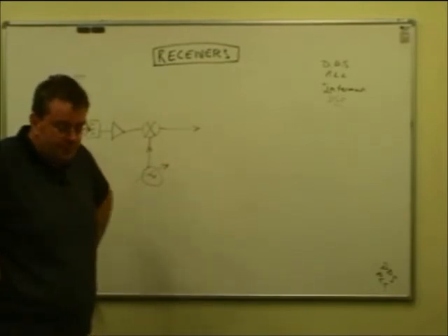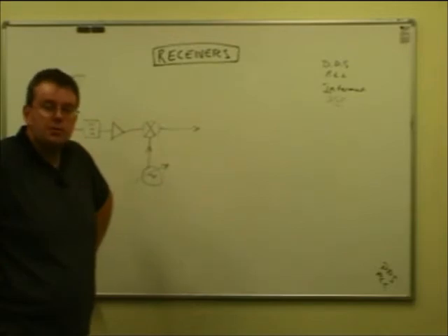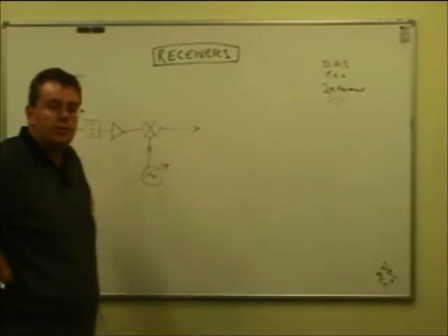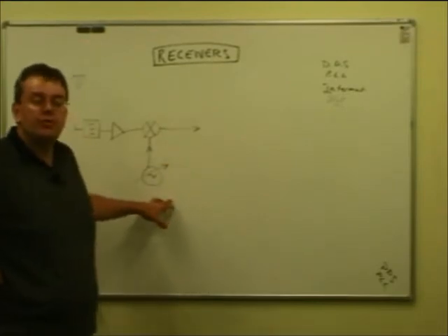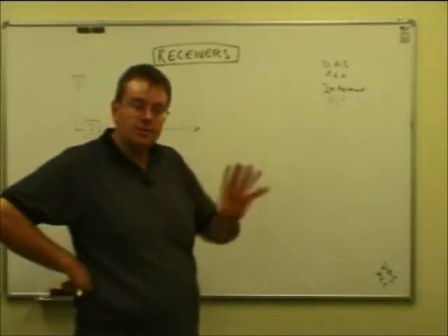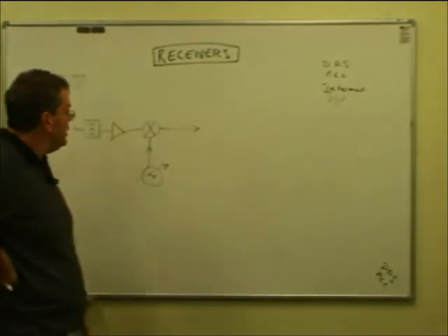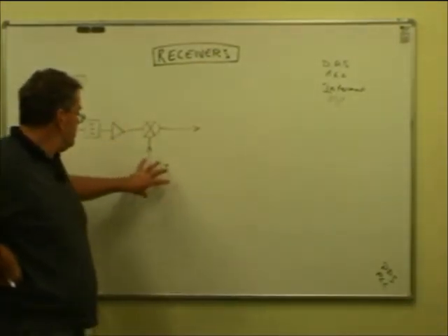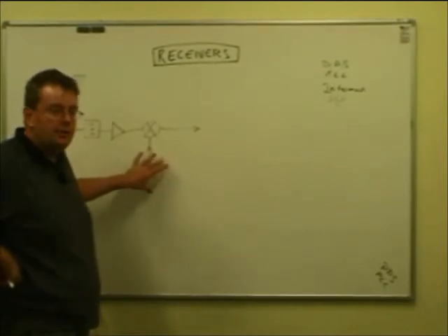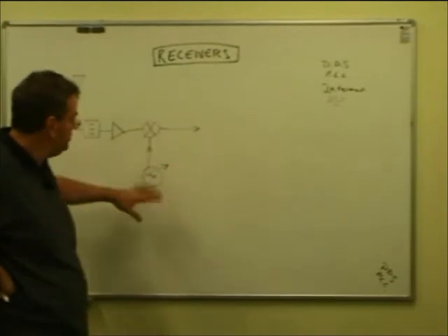But to make it easier to have digital displays of the frequency you're operating on and for various other stability reasons, see the problem with those oscillators is what's called free running, and they can drift a bit. The stability can wander around a bit. In the 70s and 80s, phase lock loop technology was introduced for the local oscillator. And you can read about it. I won't go into any great details because it's a subject on its own.